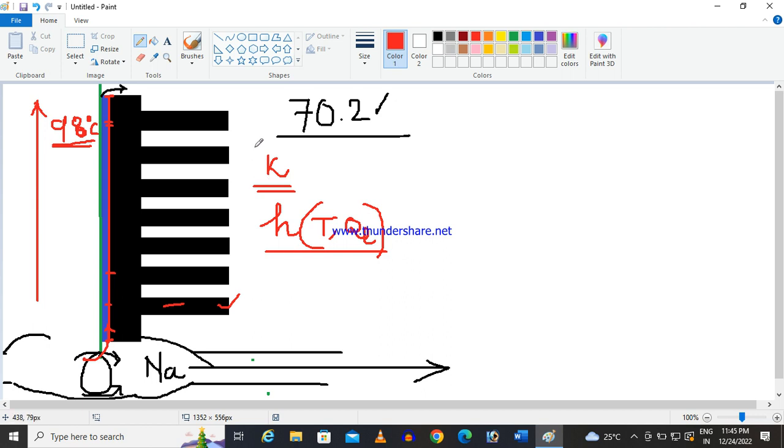Okay, so today we are basically going to discuss the other part. The valve portion is very simple. It's a normal gate valve, but the challenge is to design the fin, because if you increase the number of fins, you have to machine it from a forge, because welding is not advisable.